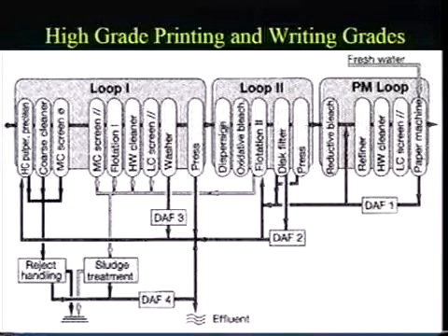In loop 2, we're going to do dispersion. At the higher consistency, we're going to do oxidation bleaching, because that works better at the high consistency. Then flotation to remove ink. And then a disc filter and press, again, to isolate the water from our next step. It will also, the higher consistency is going to help us with our reductive bleaching. And then we're going to maybe do a little refining, and then cleaning and screening.